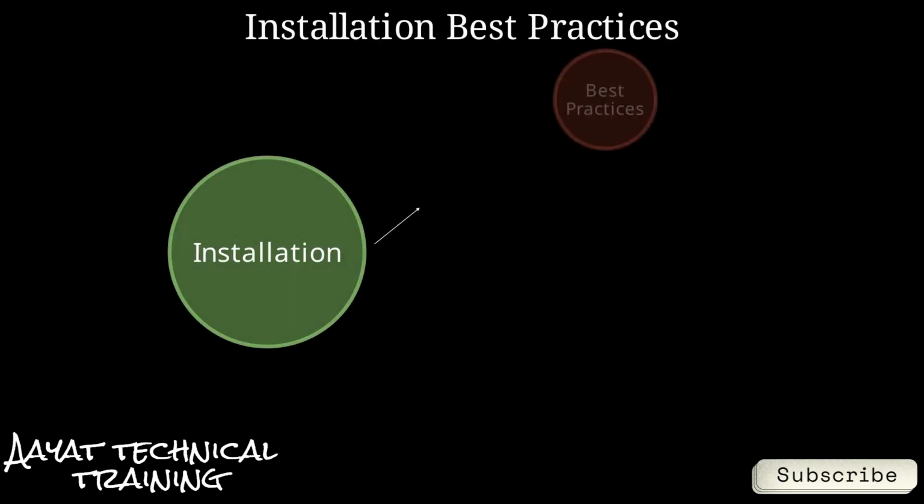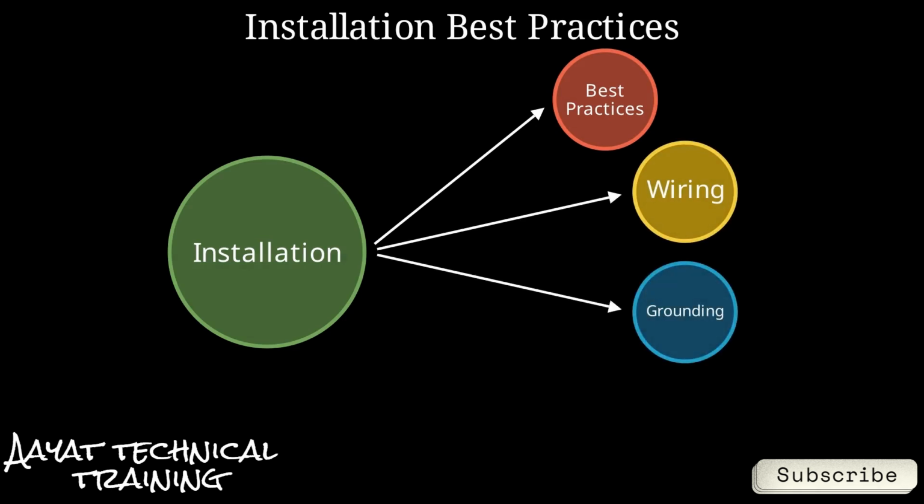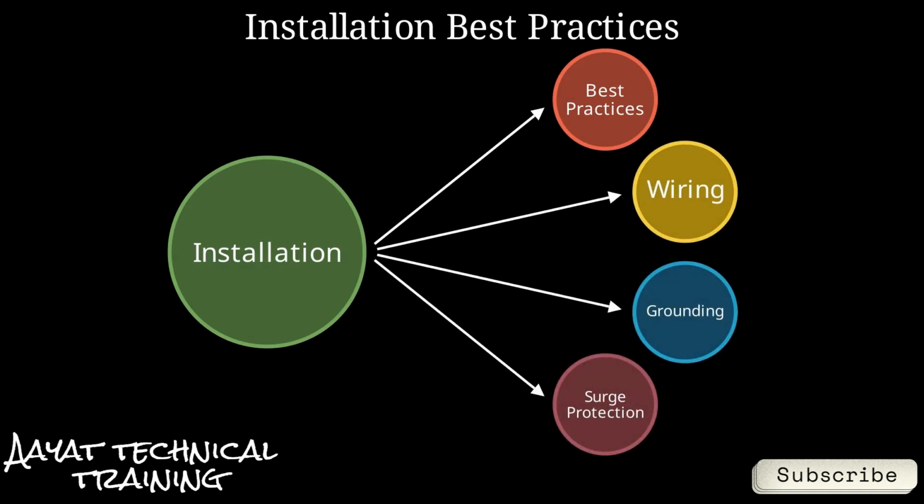For reliable BMS operation, use shielded twisted pair cables for analog signals, separate power and signal cables, label all wiring and I/O points, provide manual override switches where needed, and ensure proper grounding and surge protection.